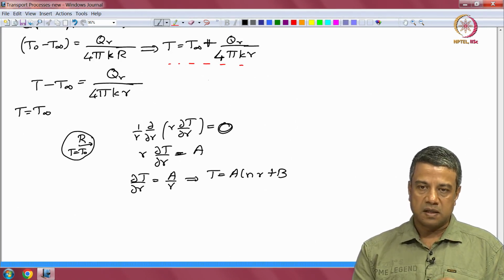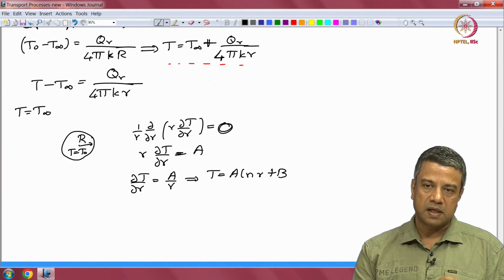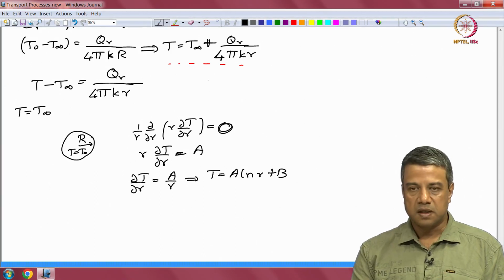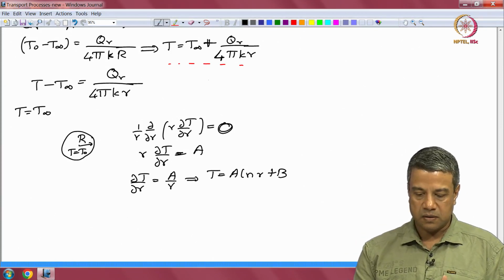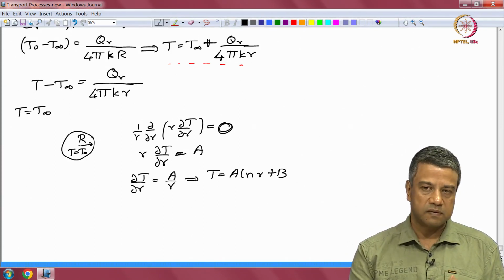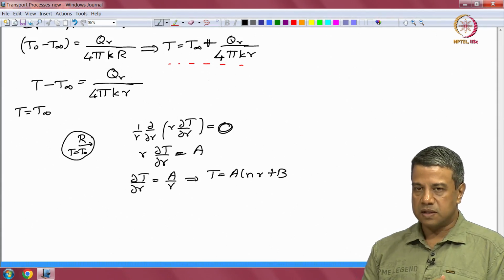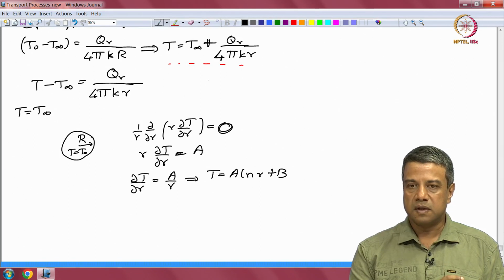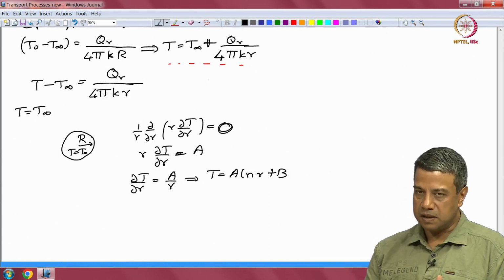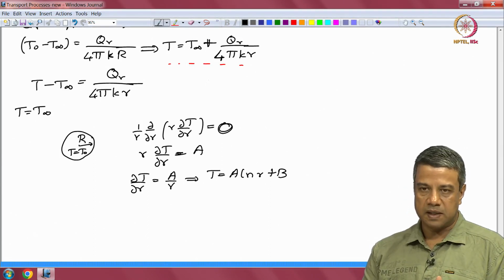One cylinder in an infinite medium does not have a solution, because the solution for the temperature has a logarithm in it, and with that you cannot satisfy a constant temperature condition far away. So, the diffusion equation for a cylindrical coordinate system outside of a cylinder in an infinite medium does not have a solution, and therefore, in order to get the solution, one has to take into account the finite length of the cylinder in the third dimension perpendicular to the plane.